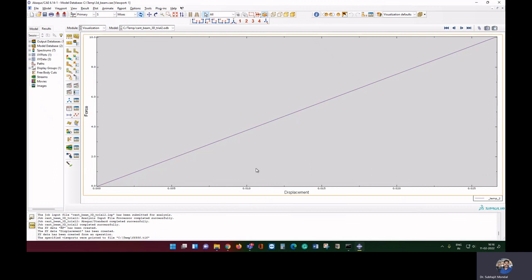We tried the convergence study using linear element and then we chose quadratic element, and we have seen that quadratic element is giving good result in comparison to the linear element, in that sense with that limited number of elements. Though if you use a larger number of elements, then linear element can also give good result.